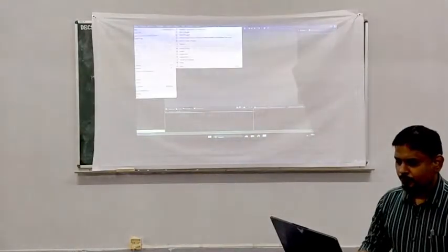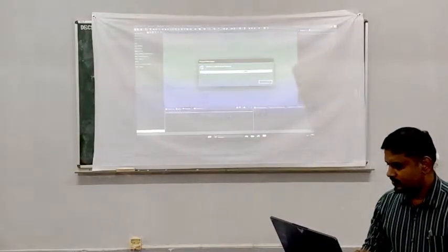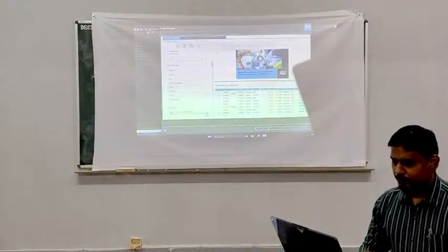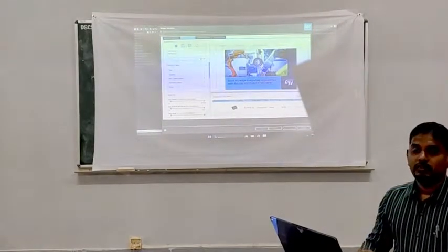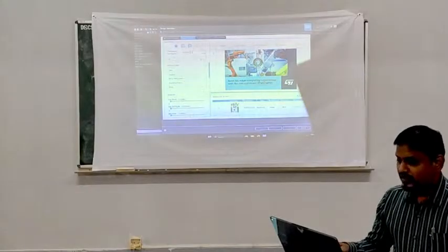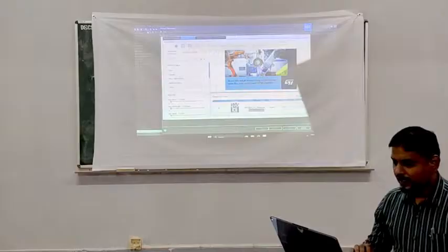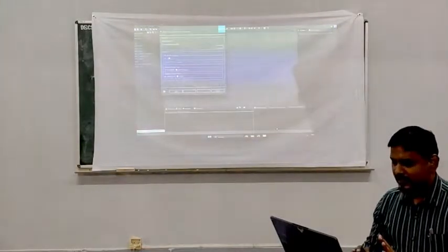See here, board selector, and just type Nucleo L476RG and just select this, and here on the bottom right side it will show. Just click on the board and click Next.